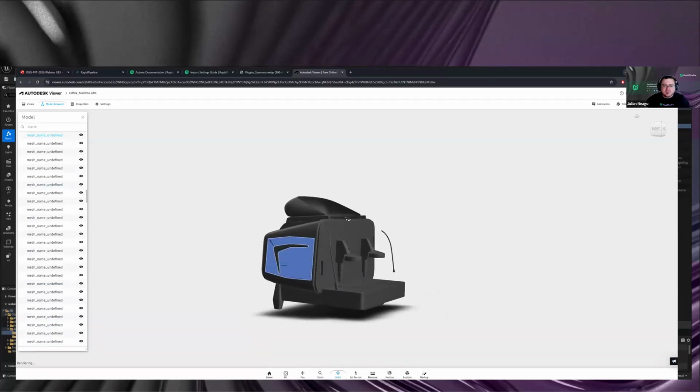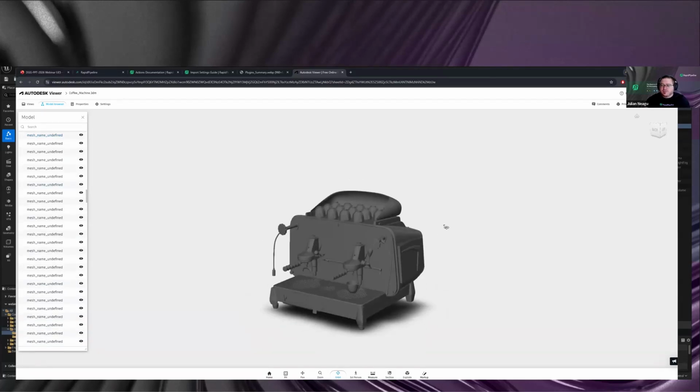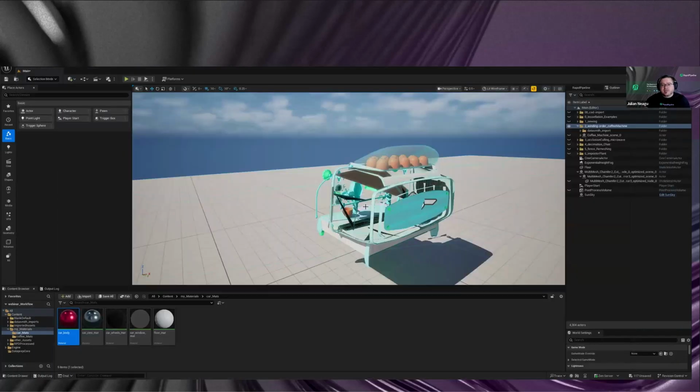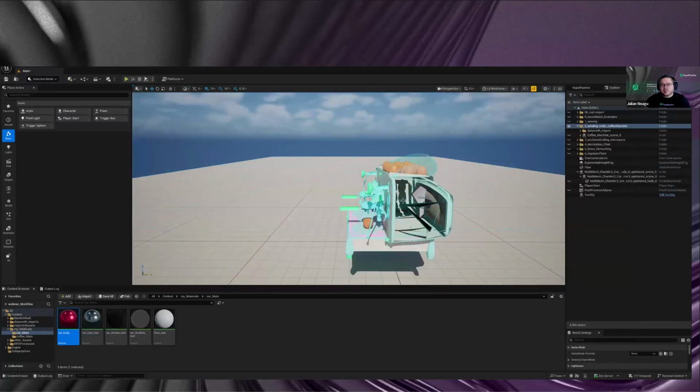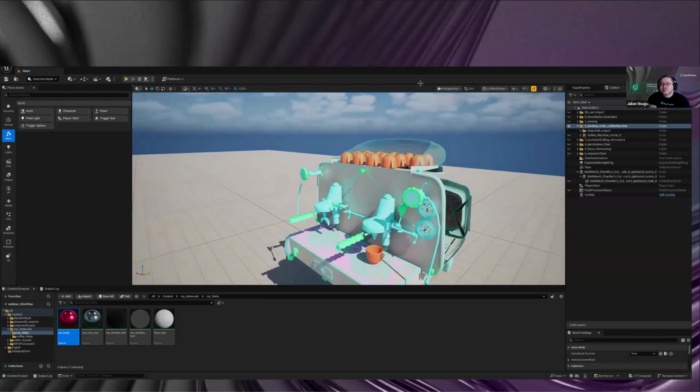It's not the perfect asset, which is great for our use case, because what we will get here, and this is especially visible in Unreal, I think, if we would import this into Substance Stager or any other kind of DCC where we have a different rendering technique, and maybe we don't have double-sided faces or double-sided materials rendered, then we wouldn't even realize that we have a problem here with the winding order. And in Unreal, of course, by default, we want to do the backface culling also for performance reasons. And then, yeah, we get problems with this. And basically, we can fix that on import.